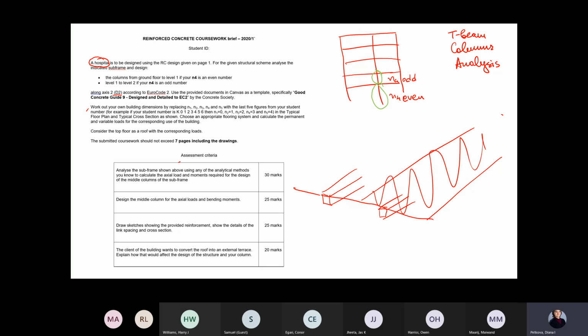Technically, what you need to do, of course, you remember, if you have the span, which is roughly about 4 meters, I think I calculated 4.5 for my example. The distance between the axes of the beams would be about 4.5. So each beam will take half of the load to the beam on its left and on its right. So effectively, it will be supporting this strip of the slab, and the width of this strip would be exactly 4.5 meters.